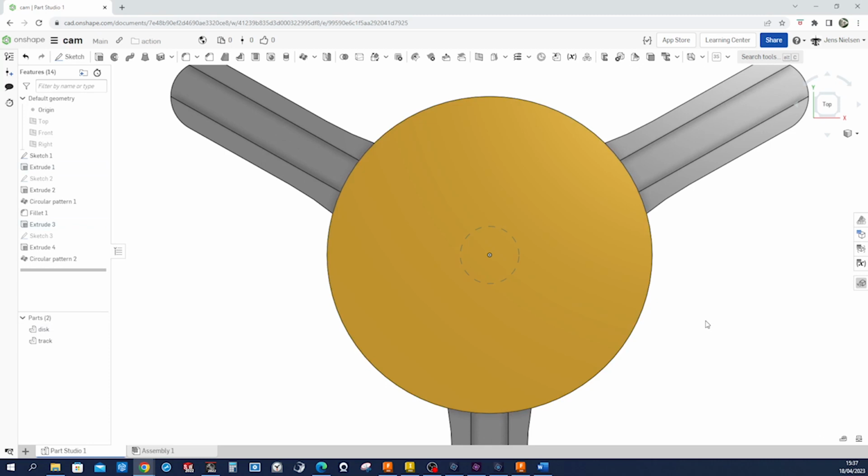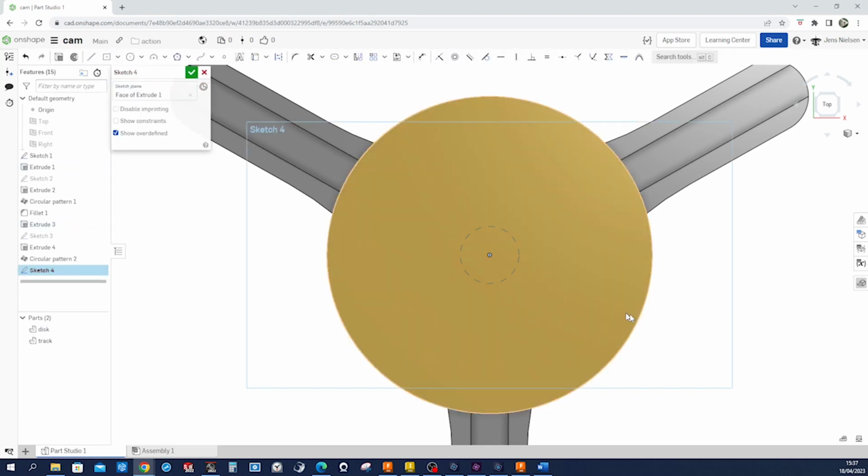So on that face, we start that sketch and start with that arc. Define that to the center here. Make that vertical construction. Give that a dimension 32. And take that over there. Give that a dimension of 42.